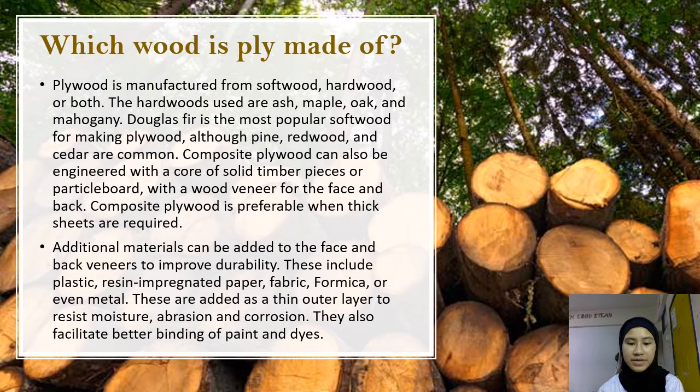Additional materials can be added to the face and back veneers to improve durability. These include plastic, resin impregnated paper, fabric, formica, or even metal. These are added as a thin outer layer to resist moisture, abrasion, and corrosion. They also facilitate better binding of paint and dyes.